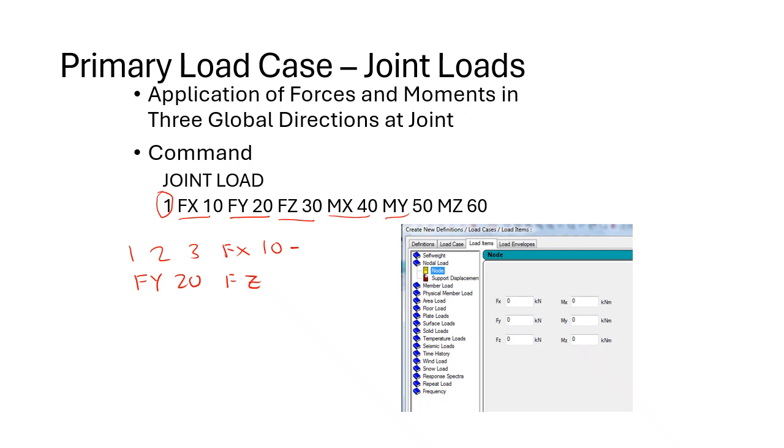And there is one more feature available, grouping. We can create a group of joints and members. So what is the benefit of creating a group? We can assign forces to a group. So when we assign here, it becomes like this: floor 1, that is a group, and then you apply the force. You can give any group name. Like we have a joint ID and member ID, so a group ID.